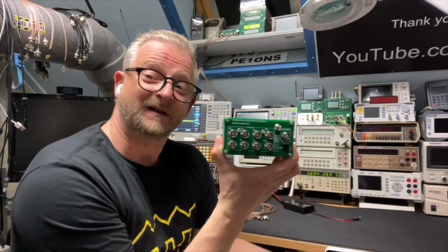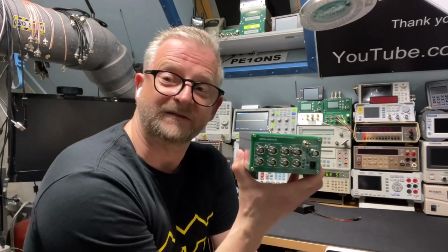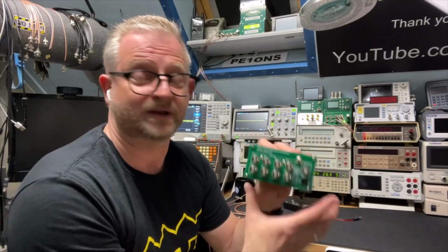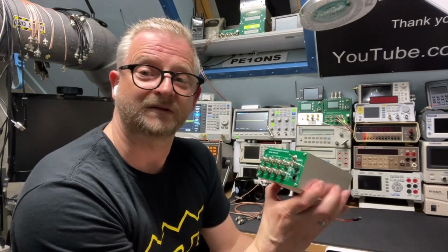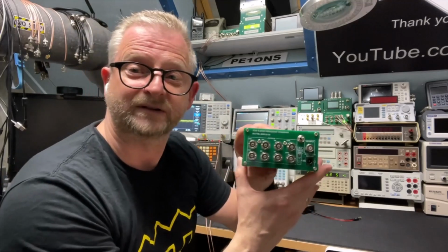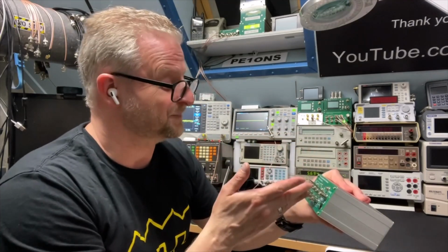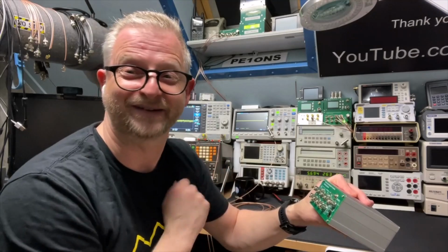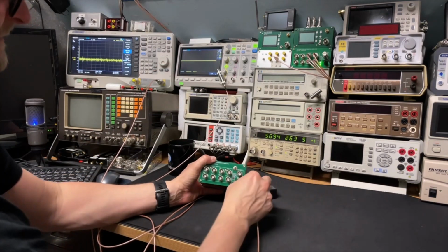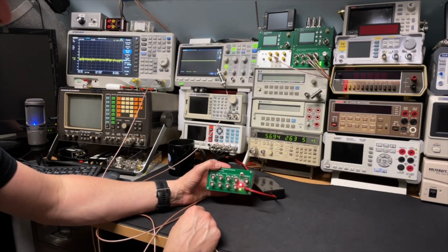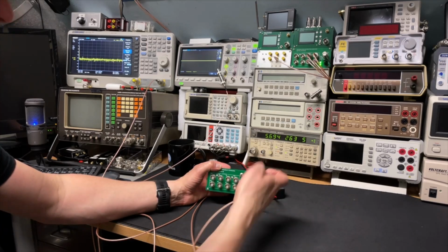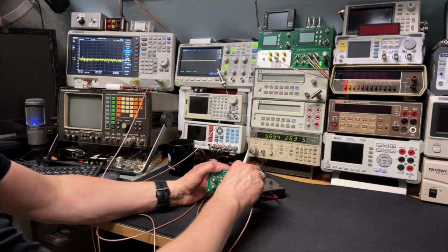This one is like the 10 megahertz. I think it also has these band pass filters on each output, but then for the corresponding frequency. So that is what I'm trying to do. I will connect it. We see how clean is the signal and if the filtering is good, because I'm also interested in that, because from this one I don't know. So let's have a look. We switch it on. Well, there will be an alarm because the oscillator is not running. Now it is, but we're not gonna use the internal oscillator. We're gonna use 10 megahertz input.